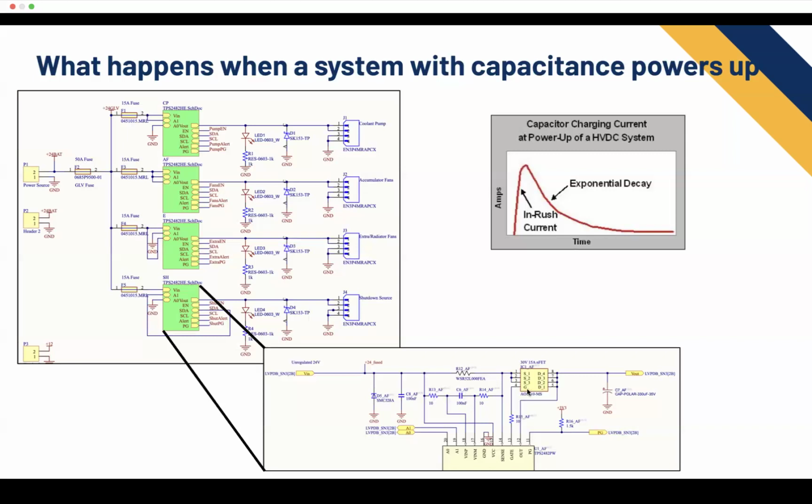And it's using the MOSFET for that. Or I think that's how this one specifically works. That's not how they all work. Some timer pins just ignore faults for a certain amount of time, and then you hope that your inrush current lasts less time than that. But yeah, is there any questions on this?